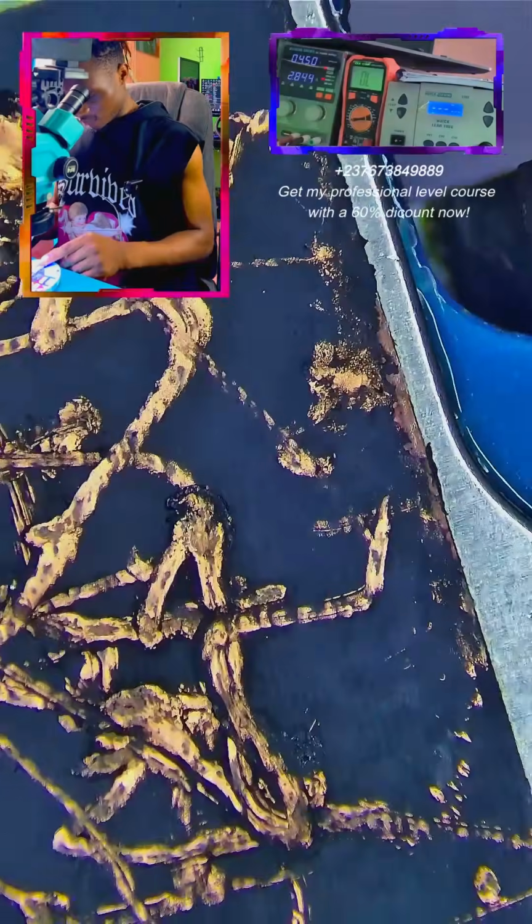So the next circuit, because this PCB is not actually heating up, we have to locate the power manager section. When it comes to this shorting fault, if you see that there is nothing heating up at all, if you locate the power manager section, you might see some little capacitors in that section that are heating up, and they always heat up just a little bit. So that's the reason why we are locating this section.